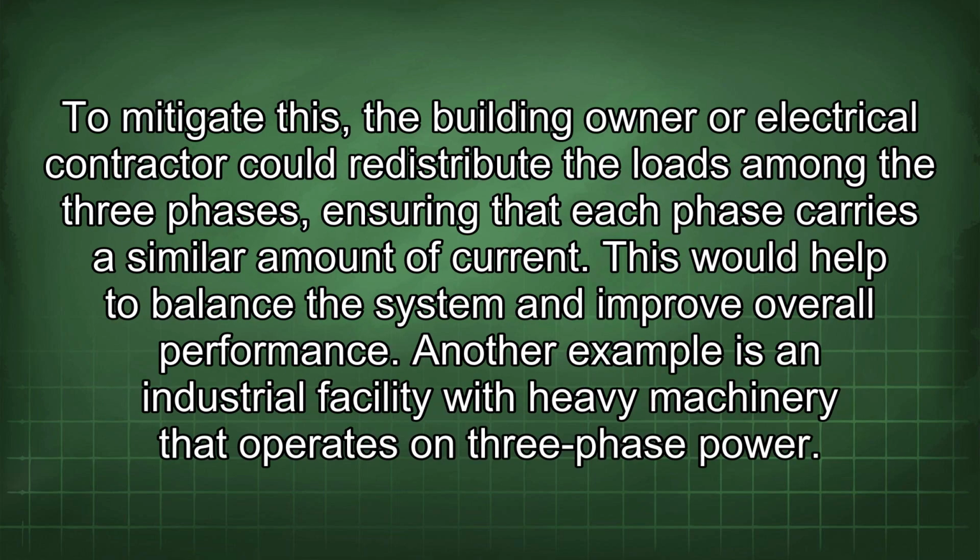To mitigate this, the building owner or electrical contractor could redistribute the loads among the three phases, ensuring that each phase carries a similar amount of current. This would help to balance the system and improve overall performance.